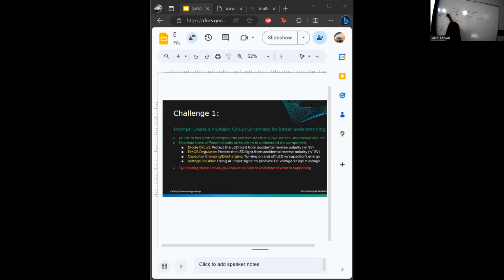Now we're just gonna go through one more like this, right? Just to show you guys what happens afterwards. Afterwards, this will become a negative or positive and negative. So now this circuit is recharging, right? But this is off. So how is this still 8.6? Because of the capacitor that was charged up earlier, right? So there's always gonna be a constant 8.6 going out here, right? It's not a perfect one though. Yeah, it's like a ripple.